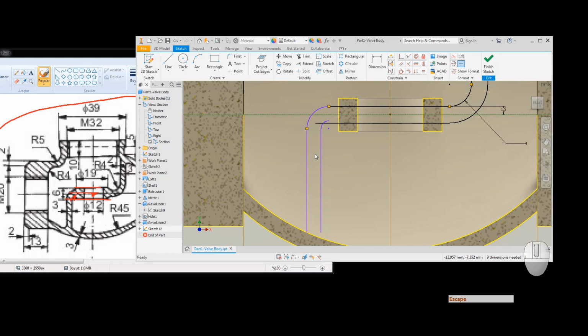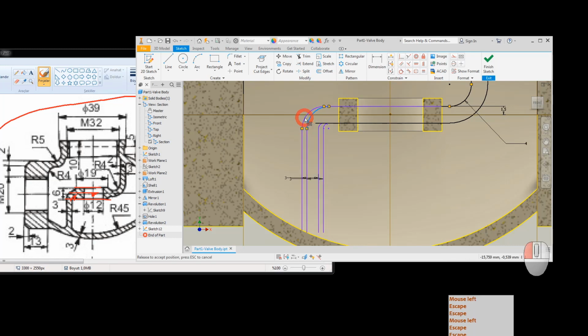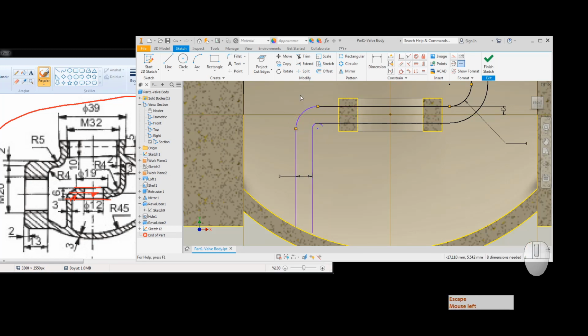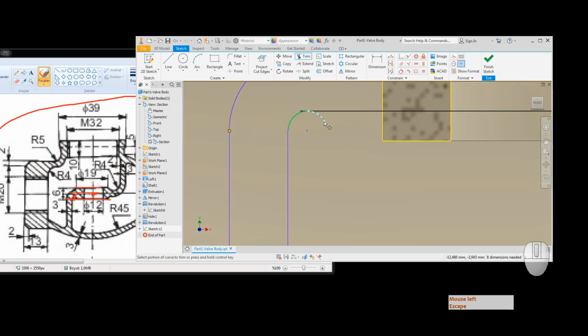The next thing, I will combine the fillet by using this offset tool. But for this, I do not want the other side offset. For this reason, I'll take the offset command and right click and get rid of this loop select option. Again, I'm on the offset command. This time I will select this portion and this line, right click, continue. I only need two sections here.